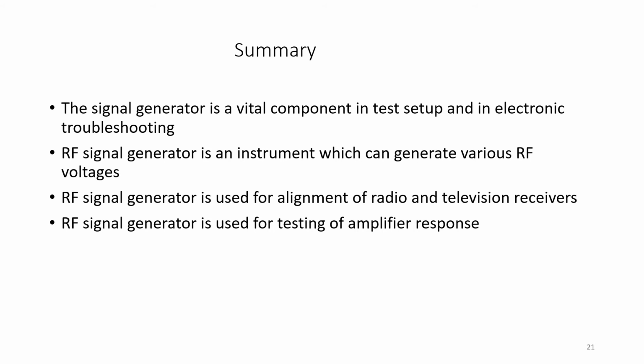For modulation, two internally generated signals are used, that is 400 Hz and 1 kHz. So you can use either the internal or the external modulating signals. The modulation level may be adjusted up to 95% by a control device. Flip-flops can be used as frequency dividers to get a ratio of 2:1.